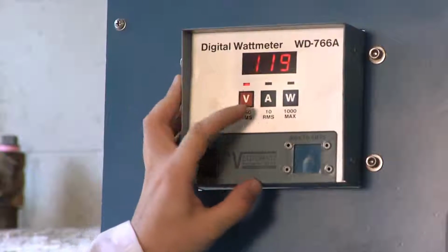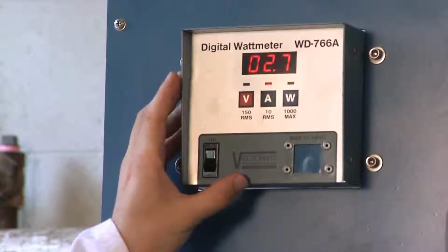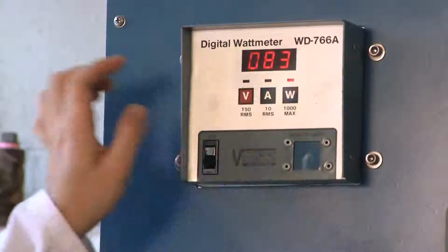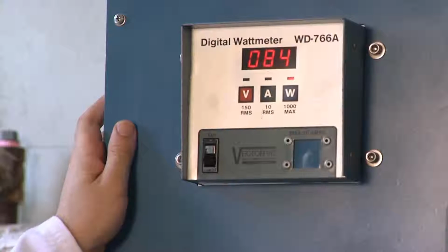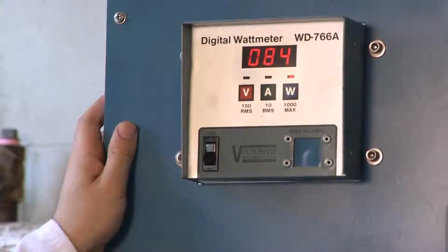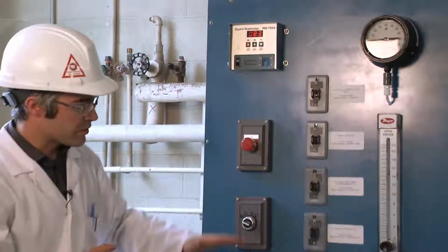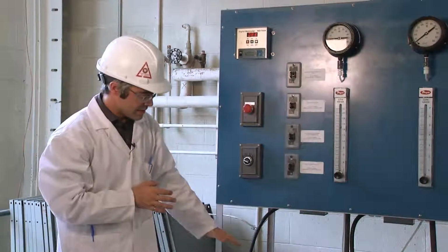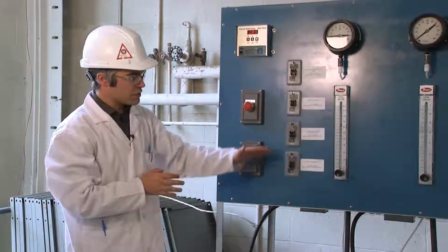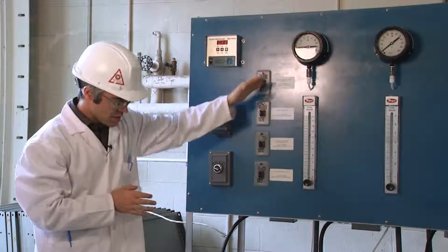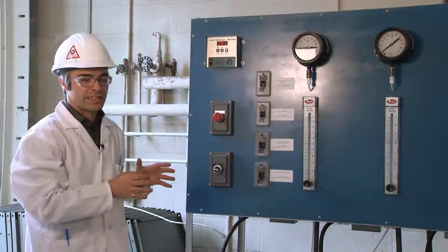We're at about 120 volts, 1.8 amps, and approximately 83 watts. All of these values together will help us to characterize the pump for this given flow rate. Now, once you have several different flow rates and pressures, you'll be able to extrapolate what applications this pump